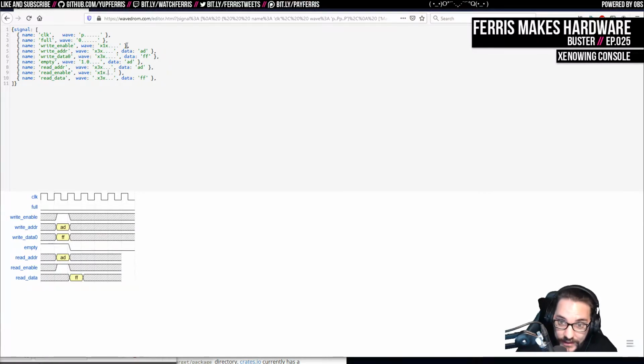Now this actually wouldn't happen, that this data valid or this data would come back, because when we issue this read, the FIFO was empty. So that read wouldn't take. The FIFO wouldn't return the data. So if we tried to read back on this following cycle, we'd get garbage.